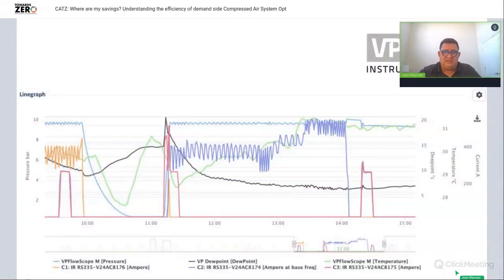I'm going to point out my little high chair here and talk about when the demand profile gets lower than what the compressors can handle. If you see this little chair looking here, that back of the chair is the only time that compressor was loaded. This is the unloaded time, and then this is the shutdown period after it.